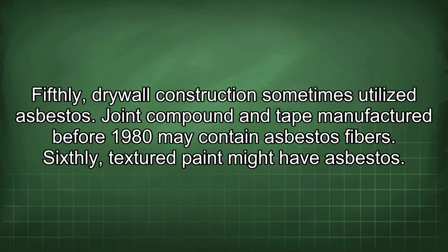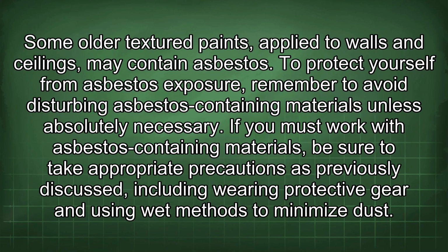Sixthly, textured paint might have asbestos. Some older textured paints applied to walls and ceilings may contain asbestos. To protect yourself from asbestos exposure, remember to avoid disturbing asbestos-containing materials unless absolutely necessary. If you must work with asbestos-containing materials, be sure to take appropriate precautions as previously discussed, including wearing protective gear and using wet methods to minimize dust.